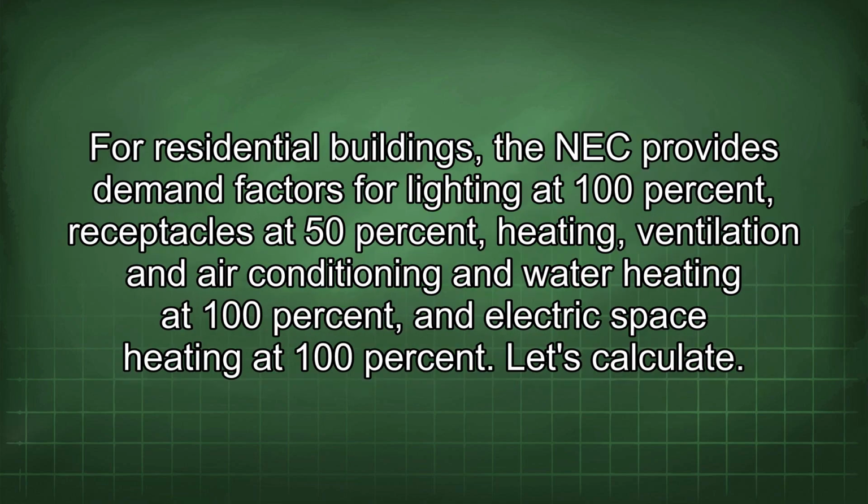simultaneously. For residential buildings, the NEC provides demand factors for lighting at 100%, receptacles at 50%, heating, ventilation and air conditioning and water heating at 100%, and electric space heating at 100%.